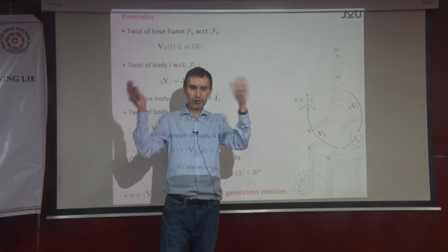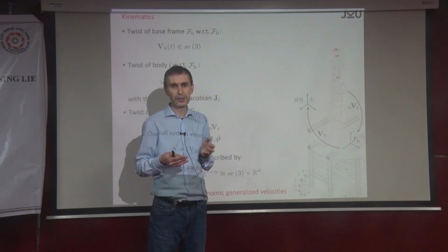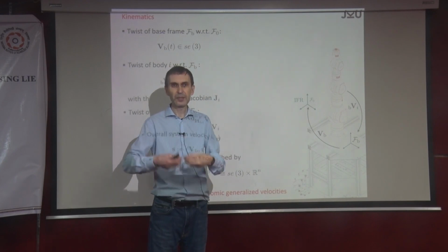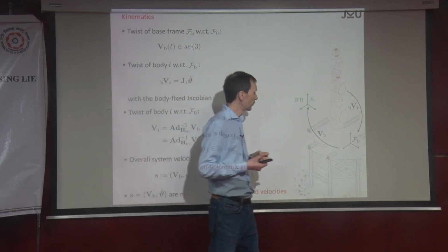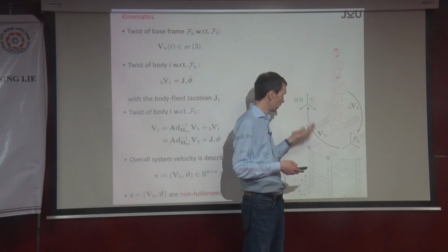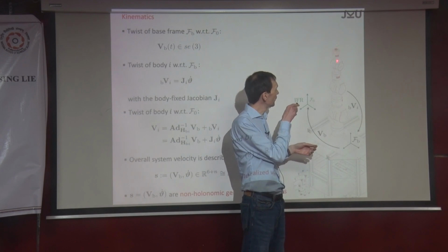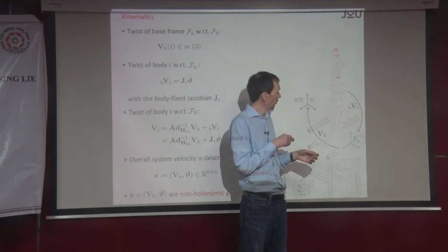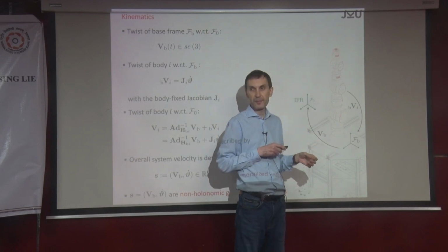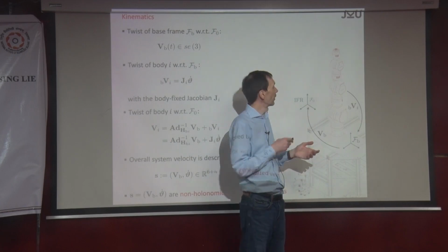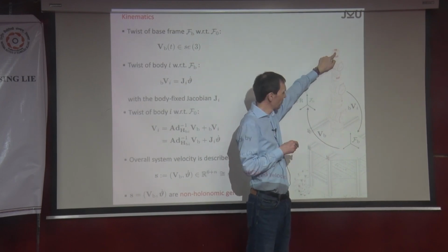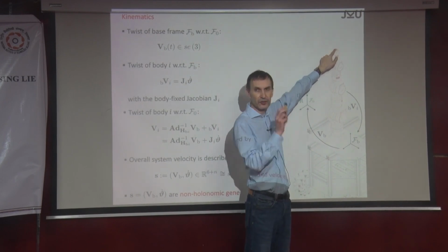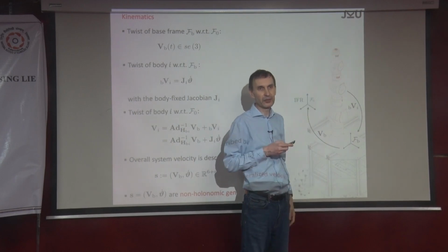I mean motions, some are crazy motions of the robot, that excite the dynamic parameters. A stupid way of trying to identify the mass of this system is by rotating about this axis, because you get nothing out of it. If I would like to identify the dynamic parameters of this last link and I rotate about the vertical axis, you don't get much.